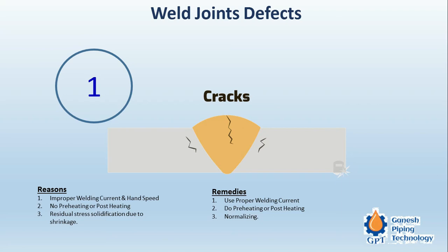So both the filler metal as well as the base metal are molten and we get a homogeneous joint. For example, these two plates are the base metal, and this is the filler metal. So this is melted some 75-80% and 25 to 20% base metal is also melted, so that we get a homogeneous joint.